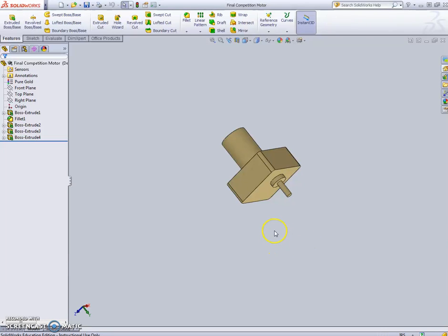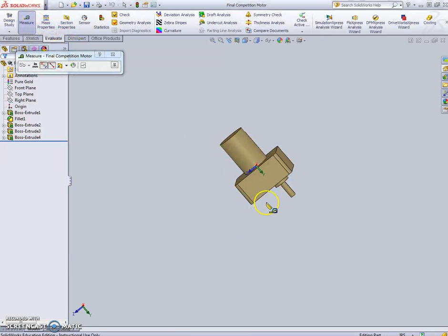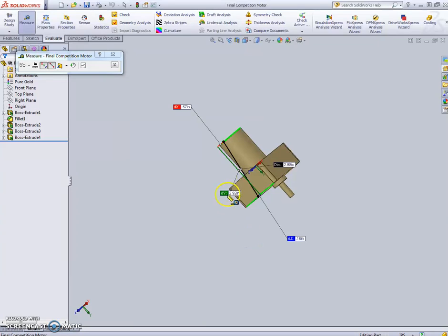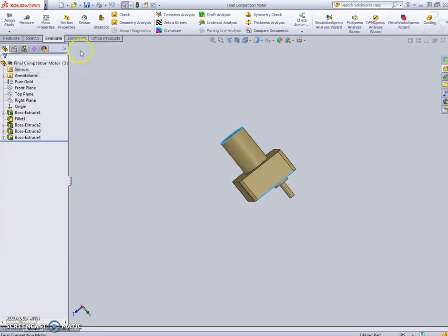You'll notice just when you're designing things in CAD, this is pretty big. If we just look at the dimensions of the motor itself, let's say we measure from there to there, what I'm looking at is the dy in the y direction, 2.9 inches, so about 3 inches, and that's not even including the motor shaft that's sticking out. The motor shaft itself, the diameter of that shaft is 1/4 inch. That will fit in all of the different gears that you're given, with the exception of the biggest gear.